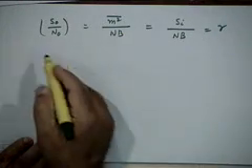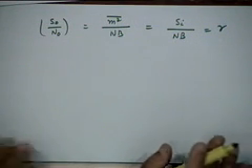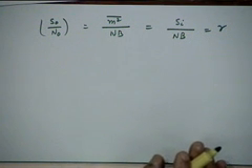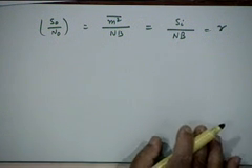Incidentally, as far as bandwidth is concerned, in some sense DSB and SSB are the same, because in DSB, although the bandwidth is twice, you know that by using quadrature modulation I can transmit 2 messages instead of 1. So, for all practical purposes, they are equivalent if we can exploit that in a particular application. Otherwise, of course, SSB. So, once again this is equal to gamma, right. So, the figure of merit so far for all the systems remains the same, equal to gamma, right.